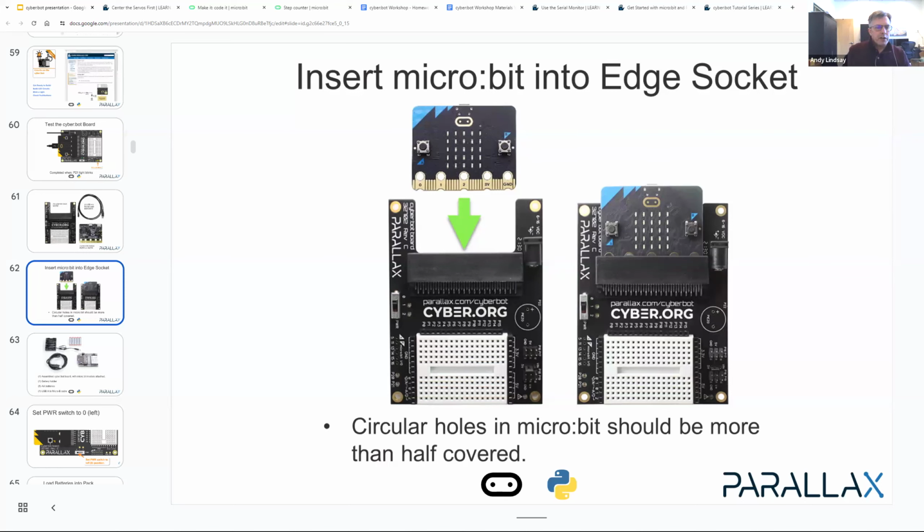Let's see, do we need to unplug the microbit from the computer first? Yes, shame on me. I think it's much better to not have it powered up when you make the electrical connections. I haven't ever heard a report of damage, but it's just a good general habit to always disconnect power when you're making any kind of circuit connections. And then give me thumbs up when you're ready for the next step.